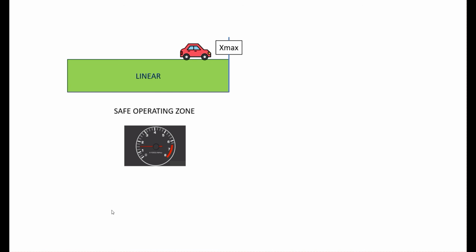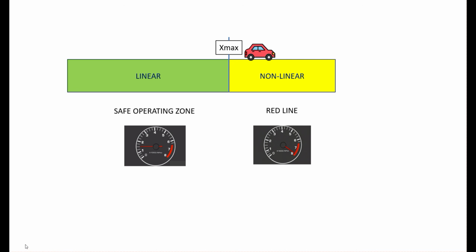I keep turning up the volume, everything's still clean and sounds great, but as you approach the Xmax limit and go over that point, the speaker starts to distort, things start to sound less clear, the bass gets muddy. So it doesn't suddenly go from clean to distorted, it's a gradual worsening of the sound quality, right?